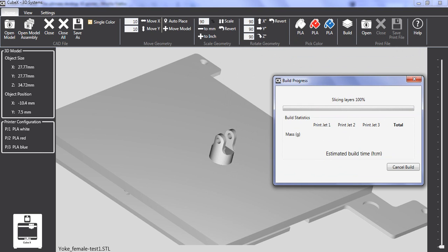I use support material as well as the raft here. Usually the manufacturer suggests using something called magic glue. I think it's a normal glue. You glue it to create more adhesion between the first layer and the rest of the layers of this part. But if you want better adhesion, you use a raft, and a raft is almost like a grid made at the beginning, and then the rest of the part lays on top of it.